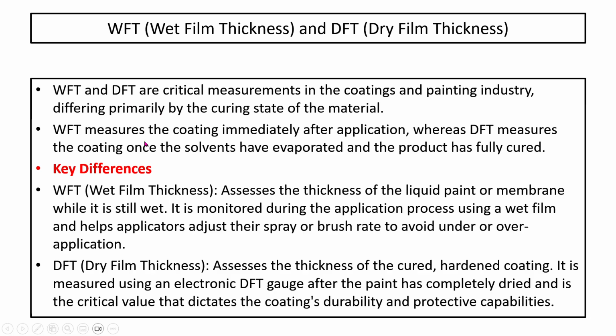So in which state is the paint? WFT measures the coating immediately after application, whereas DFT measures the coating once the solvent has evaporated. Solvent means either water or oil, evaporated, and the coating has fully cured. So DFT is measured when all the solvent has evaporated.